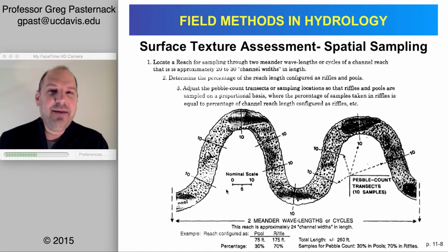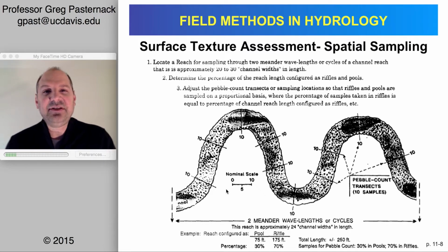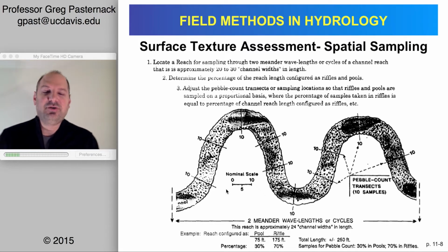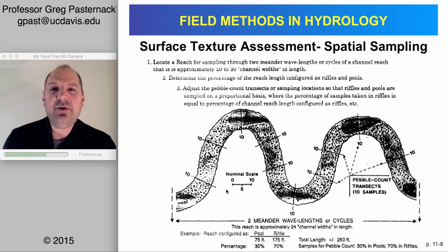Well, the mud, it could be that 1 gram of mud could be 1,000 or 10,000 particles or whatever. But 1 gram, of course, isn't even going to equal 1 grain of coarse sediment. So in order to get a grain size distribution that represents the mass, you have to sample enough of the largest particle size, which means you generally have to dramatically oversample the finer sizes.